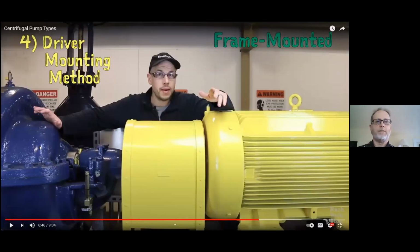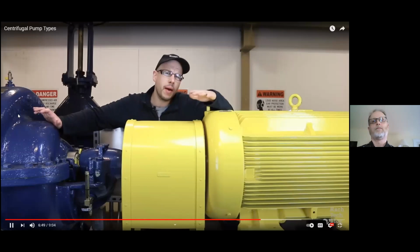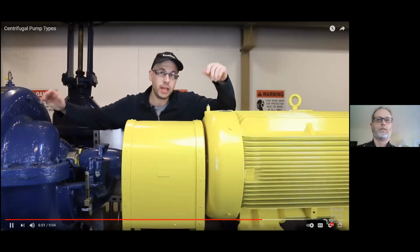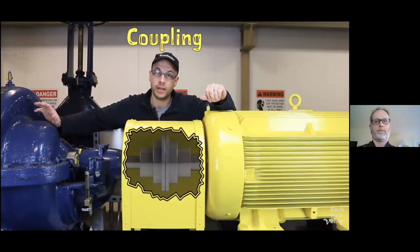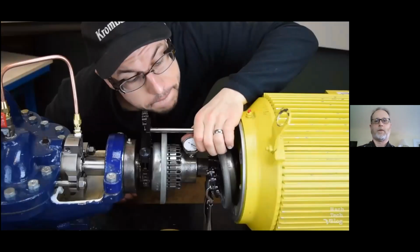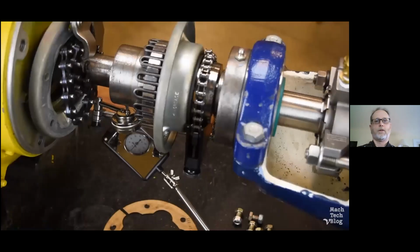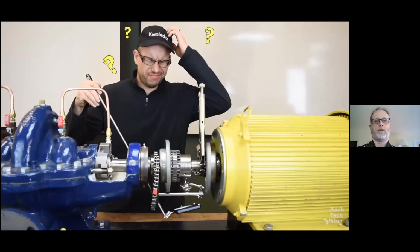So frame mounted simply means that we've got a coupling in between two shafts, as opposed to close coupled, which basically means the motor and the pump share the same shaft. If the pump and driver are two separate units, as they are here, then the pump and driver shafts will need to be connected by some type of a coupling. Now, couplings come in all shapes, sizes, and styles, but one characteristic common to all of them is that they require proper alignment of the shafts, and that can be a very finicky process indeed.